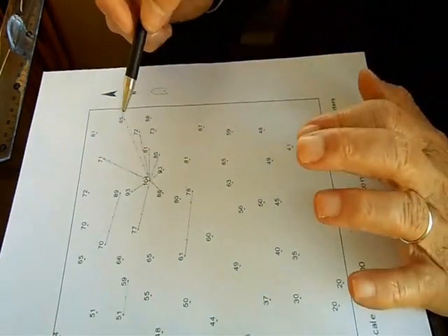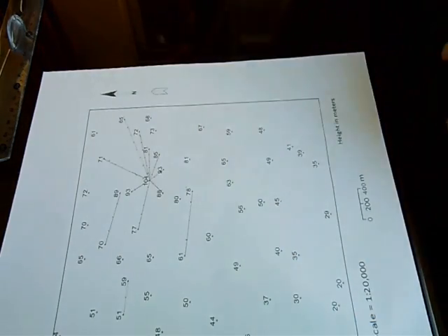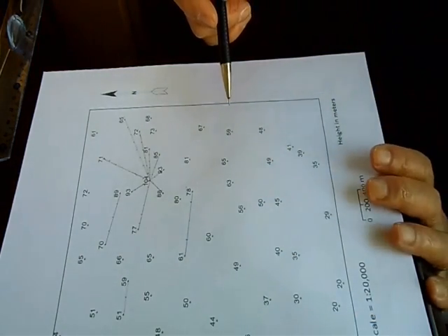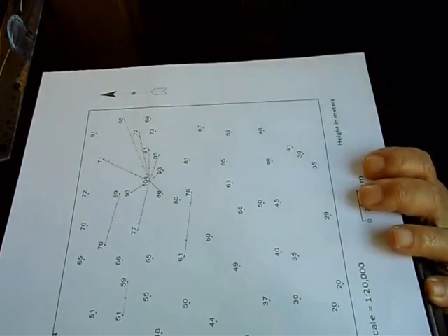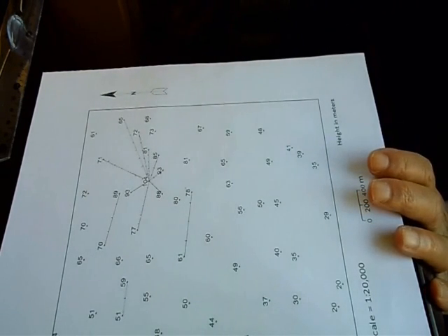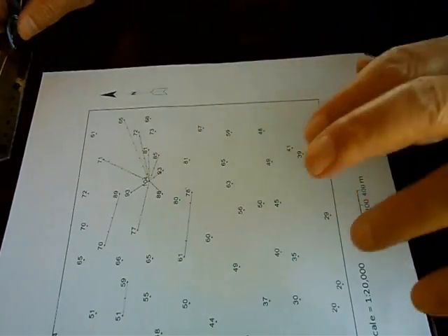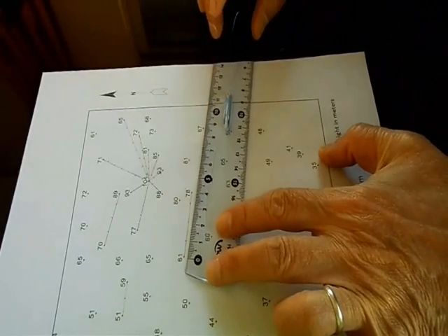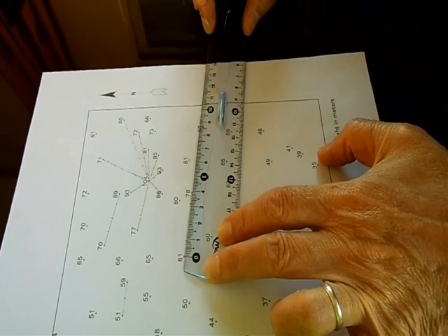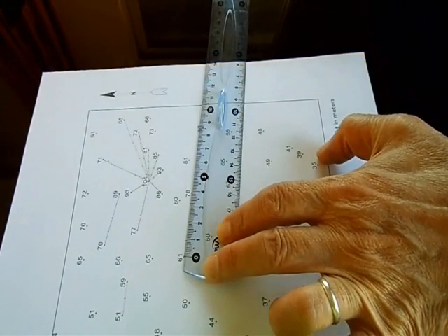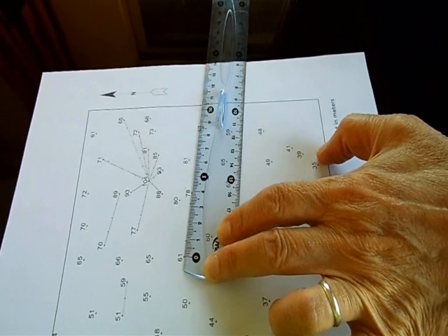So I got the locations, and in the same way interpolation may be made between the 104 points and the other surrounding points. Now one may switch to another point and connect it with the surrounding adjacent points, determining by interpolation the locations of other secondary points through which contour lines pass. We'll take, for example, these points, 78 and 61. Here the distance is 39 millimeters.